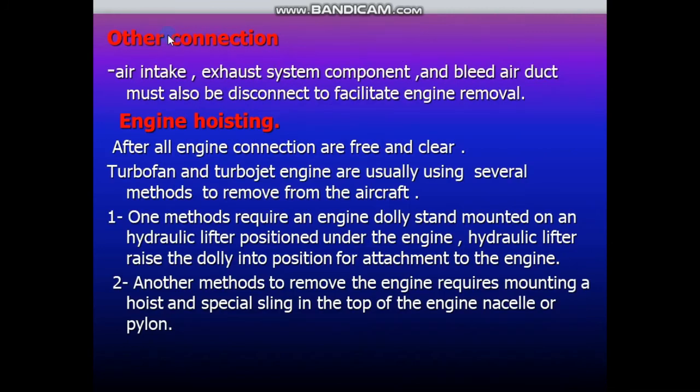After that, we have other connections we have to disconnect. Air intake, exhaust system components, and bleed air ducts must also be disconnected to facilitate engine removal. So after that, we have to hoist the engine.